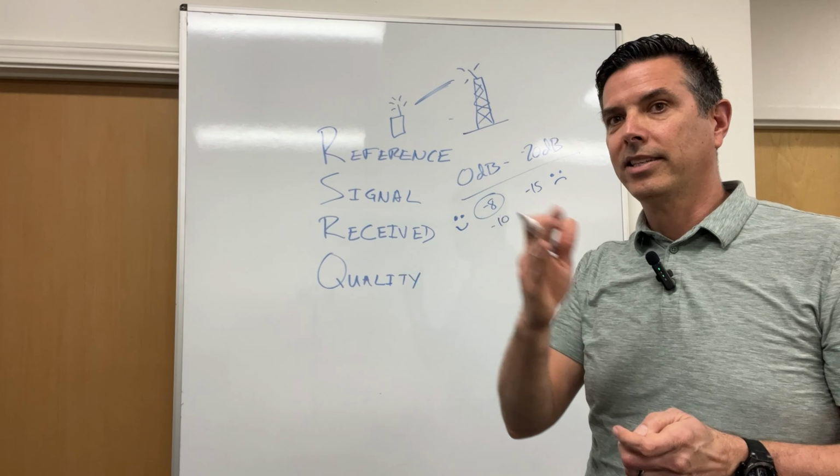For a walk test, you usually want neg 95 across 95% of your covered target area. For RSRQ, reference signal receive quality, you want to be as close to 0 as you can, away from neg 20. Neg 20 is bad. You don't want to be anywhere near neg 20. That is poor. You want it to be better than neg 10. You want that neg 8, neg 6, neg 4. Those are strong, good links to your serving cell.